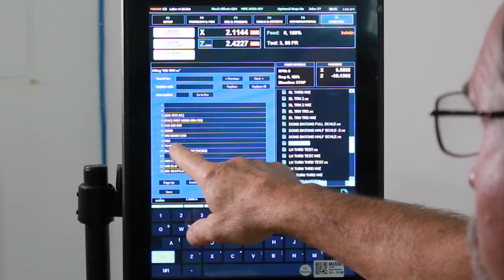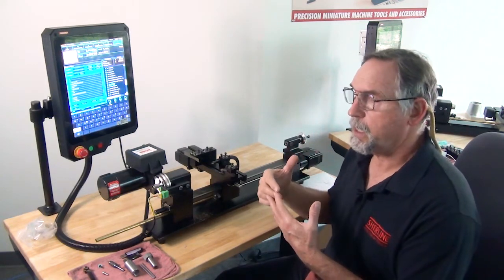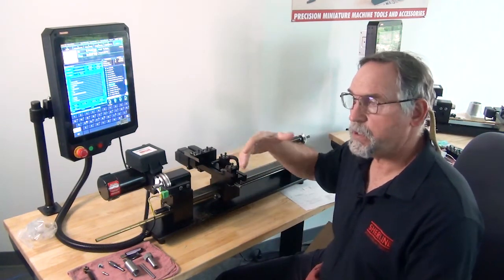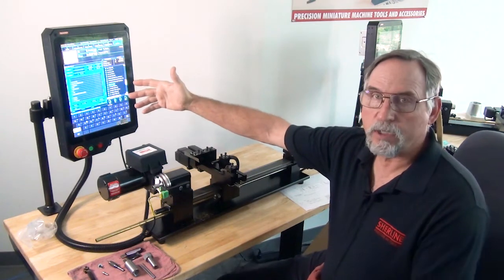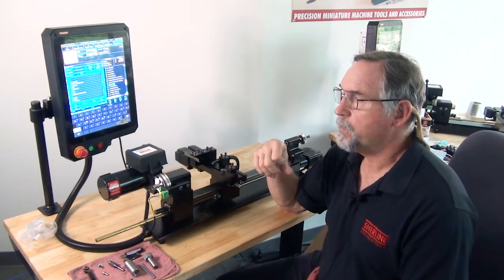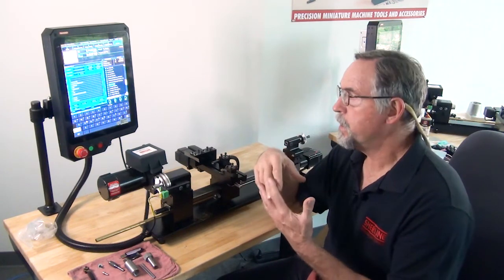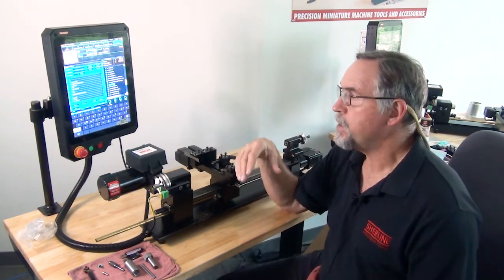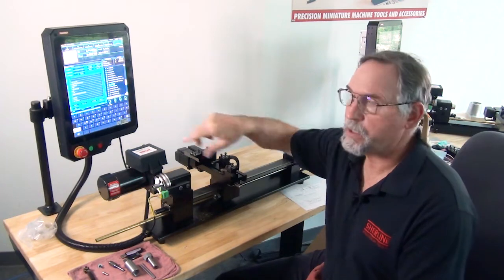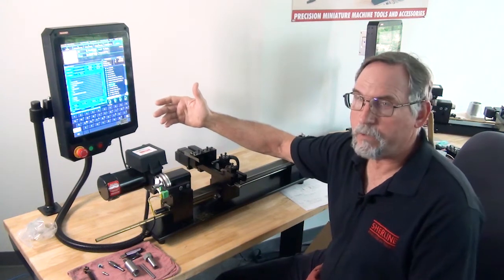The next line of code, you're just going to put an M03 in there, and that's just to turn the spindle on. Your spindle speed, once you put the G96 in there, will be dictated by the calculations of the controller. One note on this: in the calculations, they're using feed per minute in sync with the RPM. You cannot use G95, which is feed per rev, if you're using a G96. The feed rate that you will use is going to be inches per minute, which is G94.